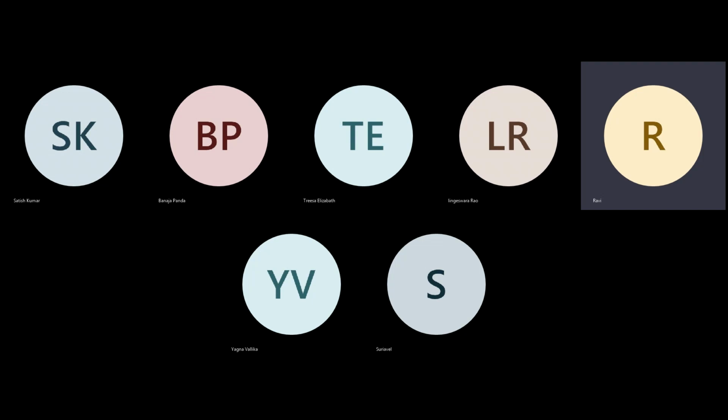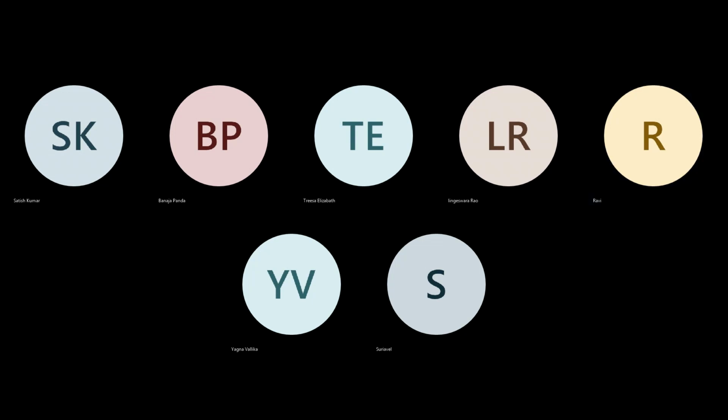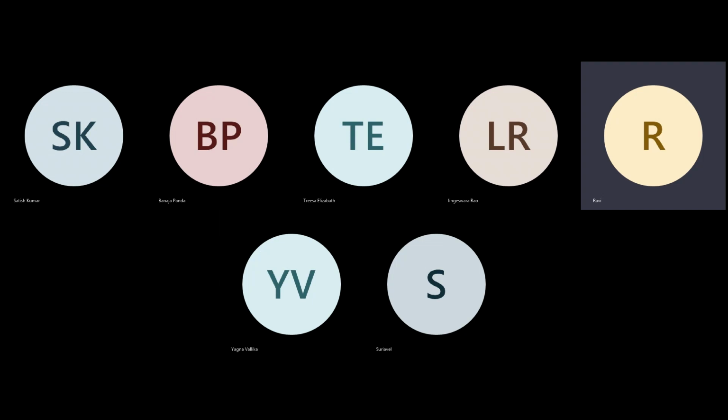Then the tool will get confused: okay, this guy is a problem. So you will have to actually design it. That's why macro placement is so crucial. Because if a macro cannot meet timing, you have control to break the macro into two pieces. Macros also, yes, memories also.